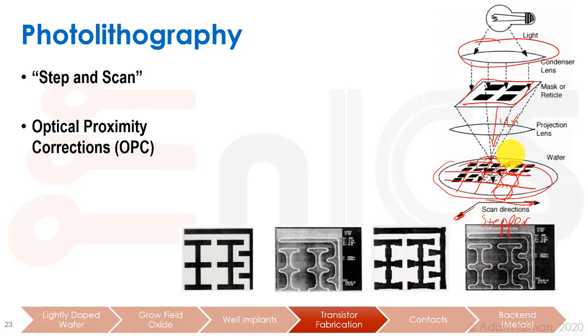Another thing is what we call optical proximity corrections. So if we take something that we drew like this, some nice straight lines here that are very right angles and so forth, when we go and make these, if we look at it, what we get are these really ugly features. And these are old technologies where it was actually pretty good shape. This still is the same as that, but in newer technologies, we get just a blob that has nothing to do with what we actually wanted to do.